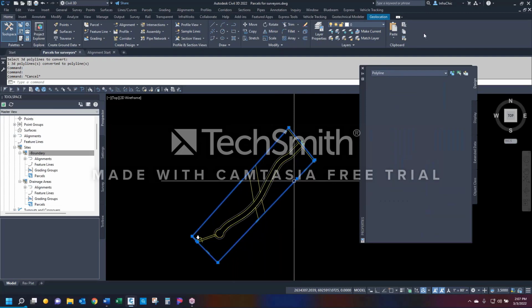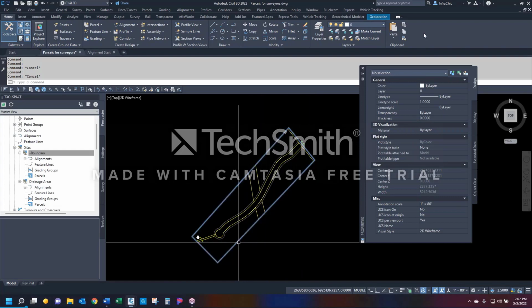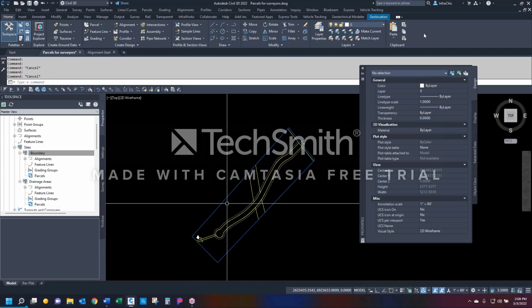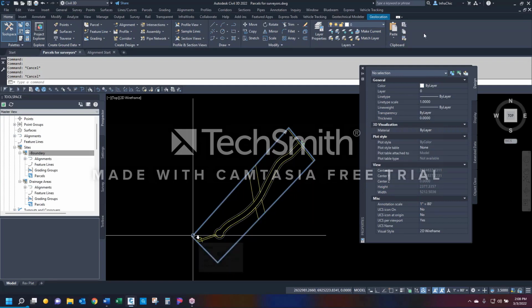Anyway, this polyline out here comes from an existing topo file. There was an iron pin over in this corner, one here. It was real basic, right? Rectangular, one in the corner, one here. Sometimes you get curves in here, and you'll have to come back with parcels and add that curve line in by hand. But if it's real simple and basic, and it's obvious from the written plat that I have straight linework, I can get away with connecting the dots with a polyline.